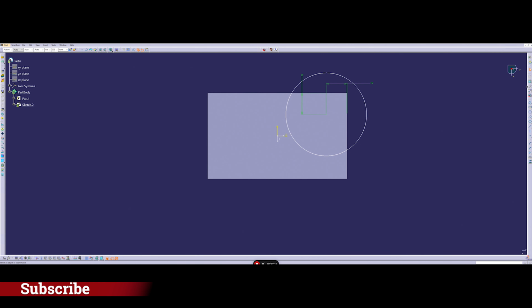So what we do here, we choose the constraint feature, we choose the line, and after that we have the dimension. Then we go here and change this dimension to 20. Okay, this is the diameter. Here we have the option to go to radius. And for the radius we can go for 15, for example, or we can stay at 10 millimeters.